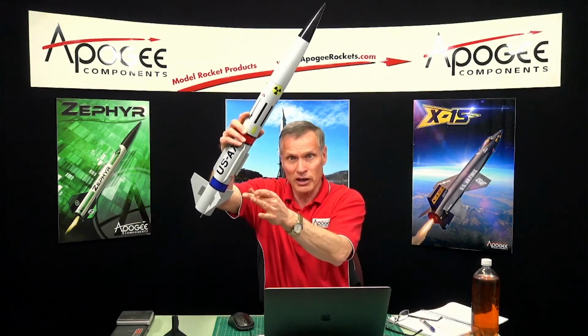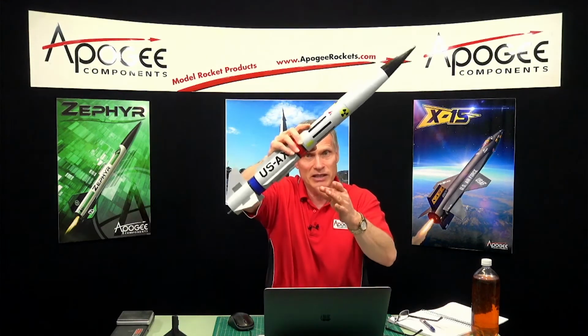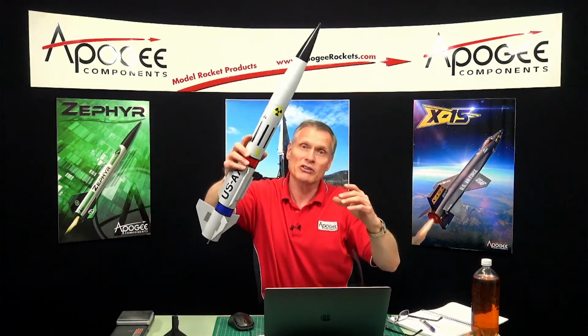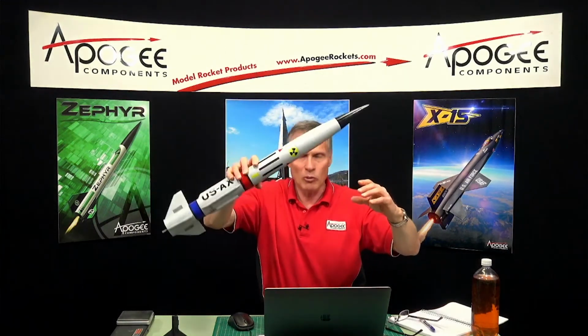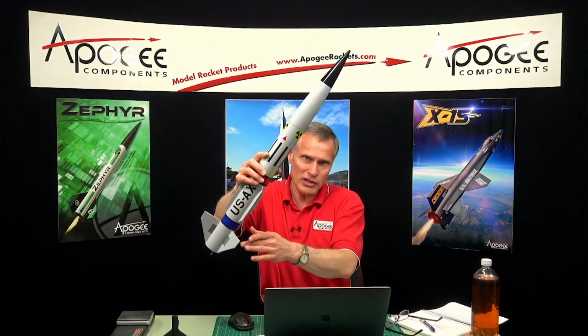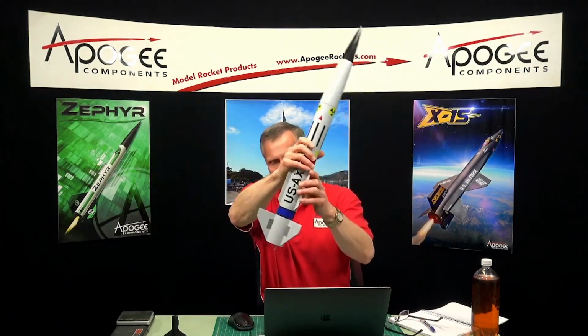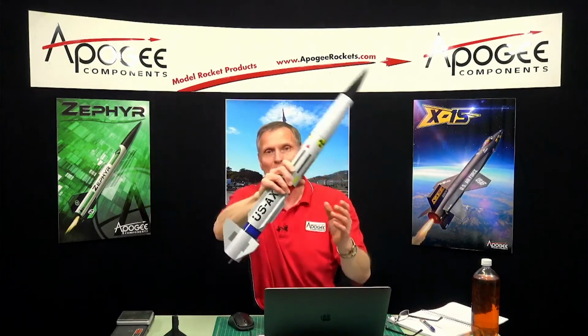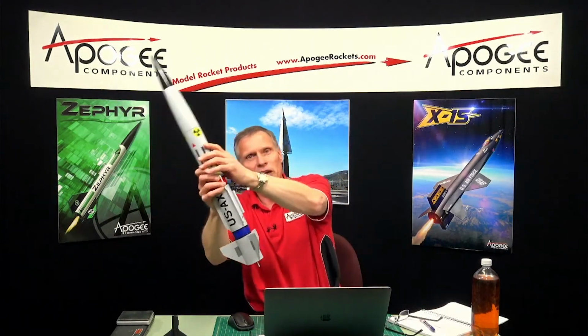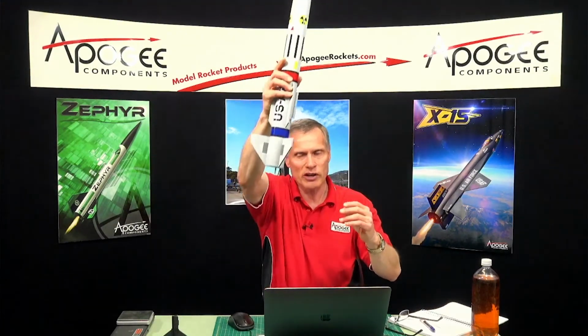You're kicking it hard this way, and the rocket goes into the wind, but then its velocity says, hey, I need to straighten out. So then it will start going back, and then because of its momentum and angular momentum, momentum is the property of matter that says, this is Newton's first law, an object in motion is going to continue in motion unless hit by another force. So that first force knocked it over, and now it's got motion going this way, and it's got angular momentum, and it's going to rotate too far. Then the wind is going to hit on the other side and bring it back around, but then it's going to rotate too far this way. And that's where that wiggle comes from: the rocket's trying to straighten itself out.